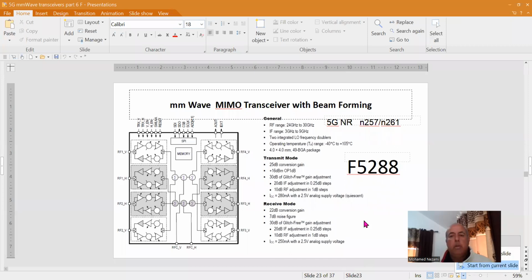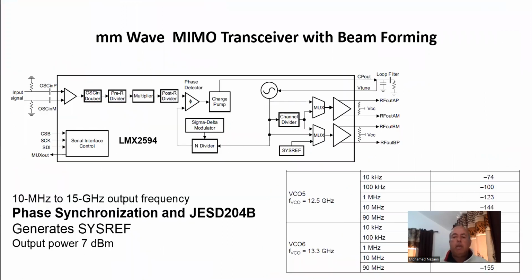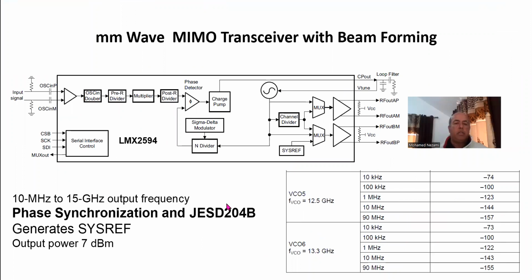So these parameters, I store them in the model, okay? My LO signal is generated from this LO. This is a synthesizer chip, the LMX2594, from TI or ADI, who owned Linear Devices? I don't remember, but it's this chip here, okay? I think it's TI. Oh, no, it's ADI. We'll see in a minute anyway. So basically, it's got an internal VCO. All you need to do is just design the loop filter in here. They give you an app that could optimize the response and give you the loop filter values.